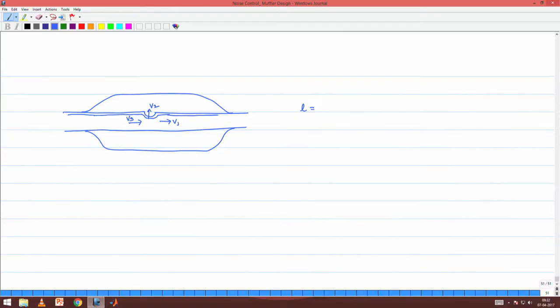is going to be L equals, firstly there is a thickness of this shell, right. This shell has got a certain thickness, you have made a hole in that shell. So, there is a thickness to this shell, I will call this T, which may be very small, but together with that there is a factor of end correction which is 1.7 times the radius of the hole itself.